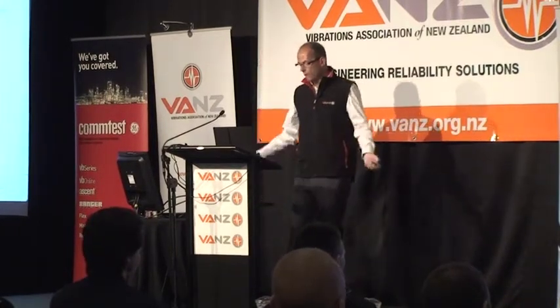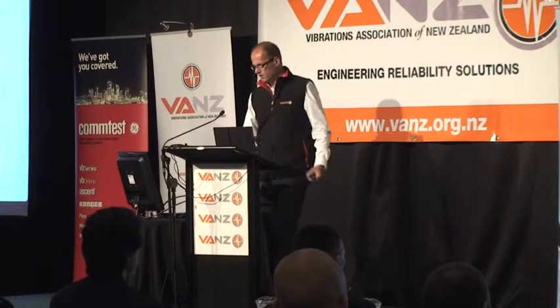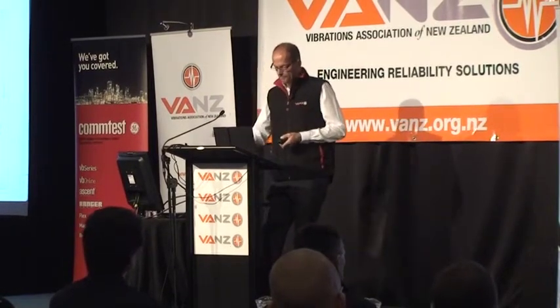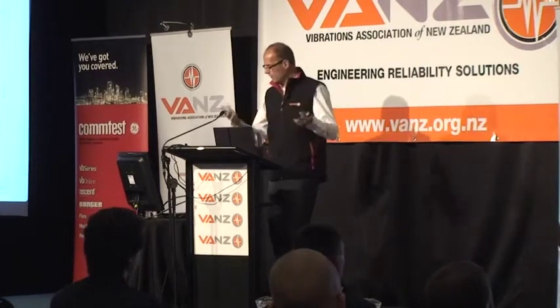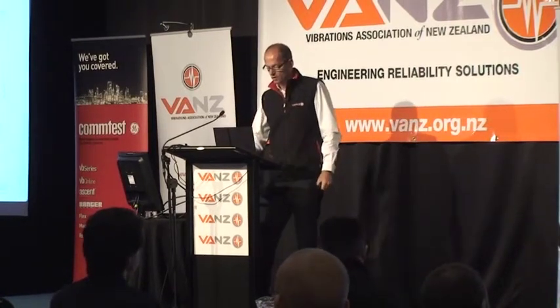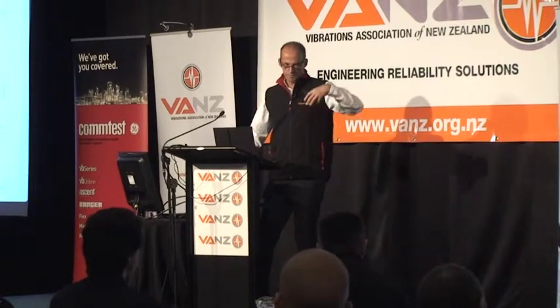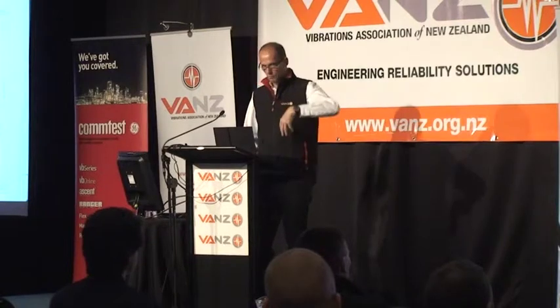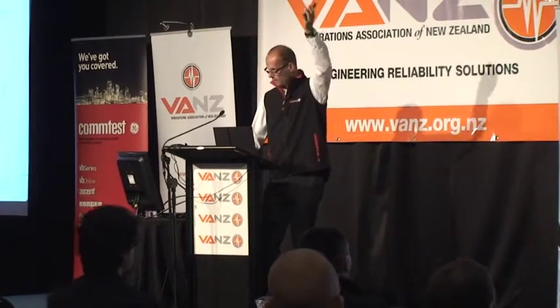So just very quickly, some of the common fault conditions. If we start from the position of a spectrum, a normal spectrum is going to have a few peaks in it. It can be more complicated than what I've been showing. But basically with unbalance, for example, we expect that peak at the turning speed, the once per revolution speed, to go up in amplitude.